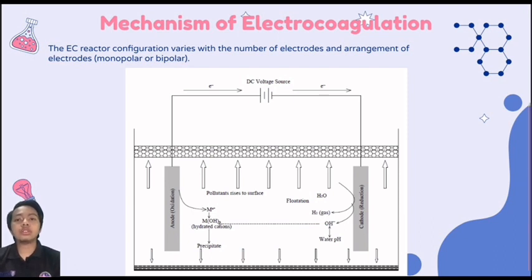Similarly, ferric ion species such as FeOH2+ and Fe(H2O)6 transform into Fe(OH)3. This insoluble Fe(OH)3 and Al(OH)3 remain in the aqueous medium and destabilize contaminants by complexation or electrostatic attraction followed by coagulation. The formation of this complex is highly pH dependent. The stabilization of contaminants mainly occurs through two distinct mechanisms.